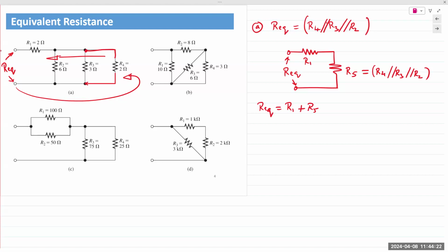If we simply look at the original circuit diagram, then there are four connections. If you simply look at that diagram, I would not be able to state that R1 is in series with R2, R3, or R4. And that would be correct. It is not in series with R2 or R3 or R4. But it is in series with the combined effect of R2, R3, and R4. It's an important difference. All right, any questions?